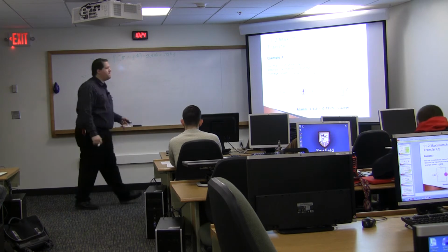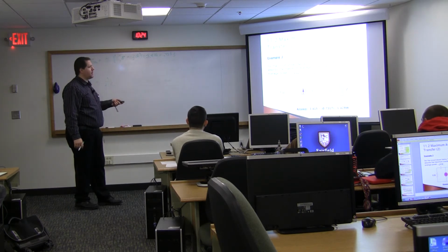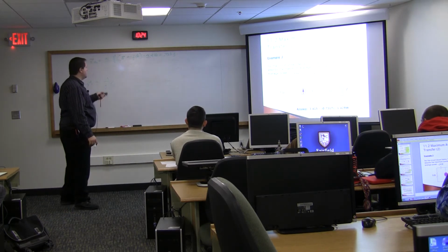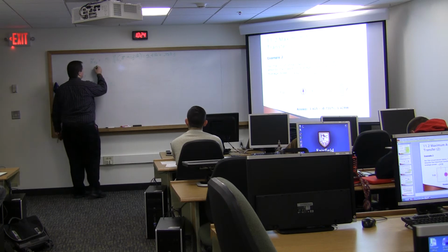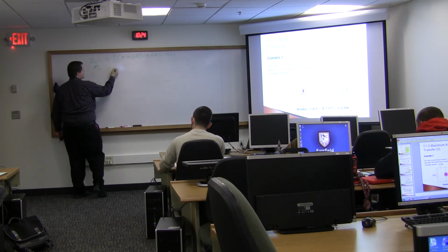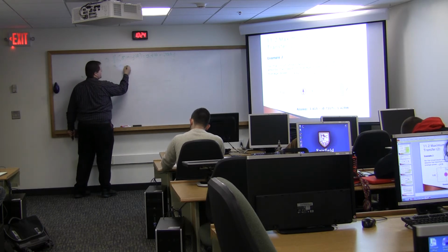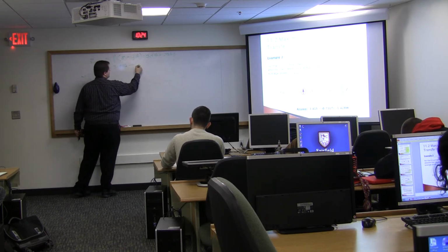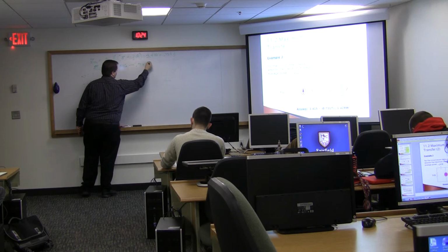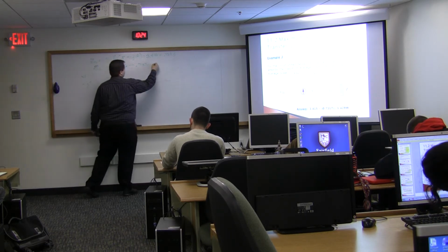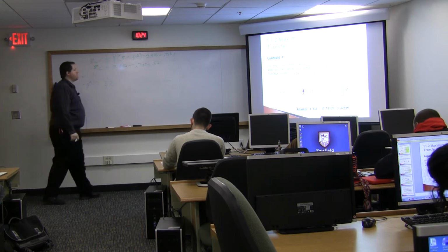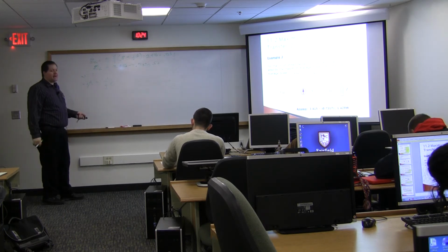So the best matching impedance is the complex conjugate of that. So here I have the Thevenin impedance being 3.416 plus 0.732j. So the load impedance that I want would be 3.416, the same real part, but minus 0.732j. And this is measured in ohms, right? It's an impedance.